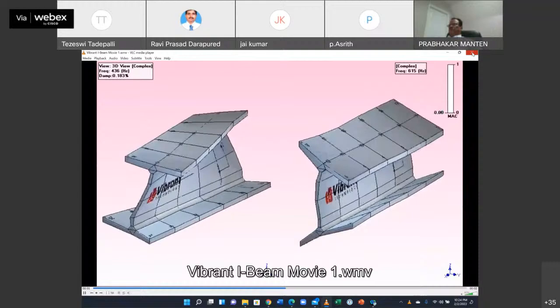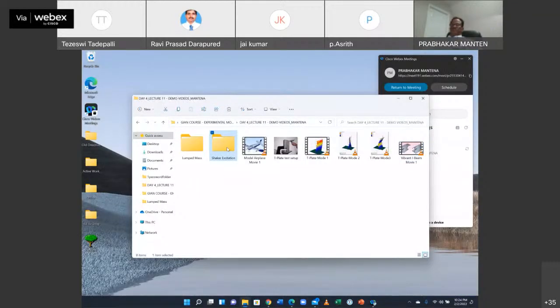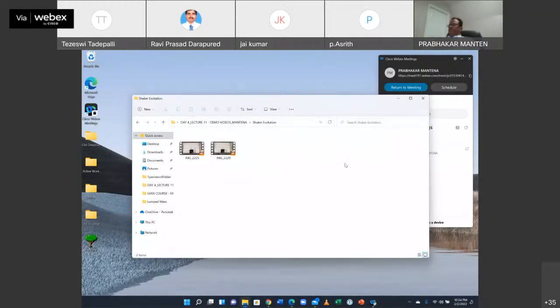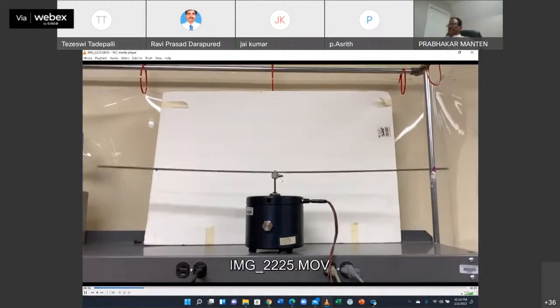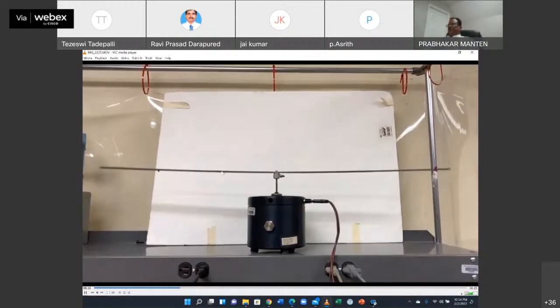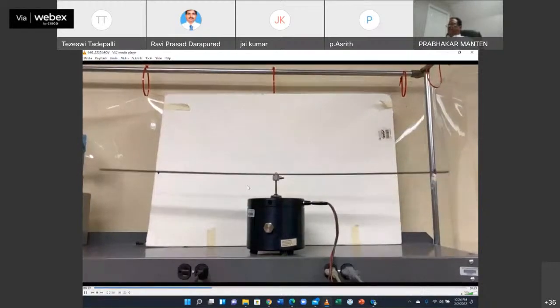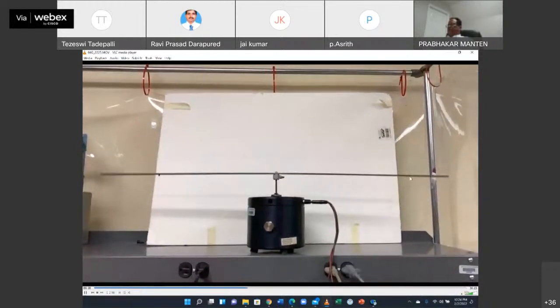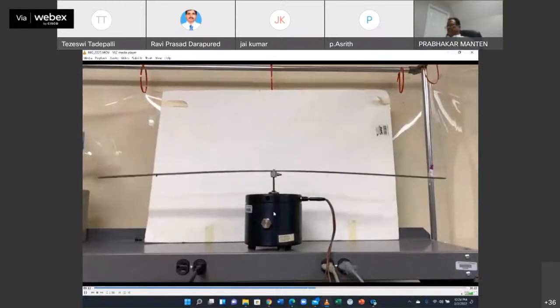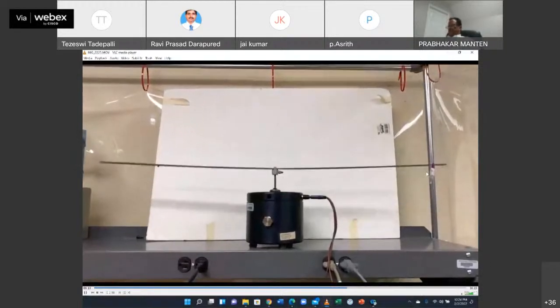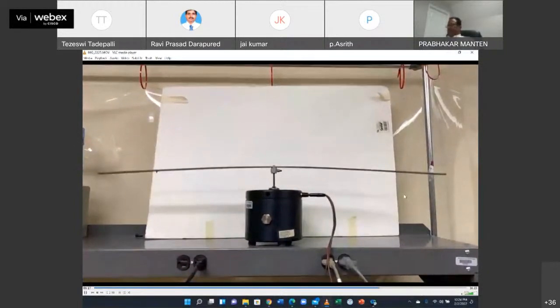And I think I have one more example, shaker excitation. This is one more thing we do in our lab here. We use a shaker setup. Tej knows all this. He has been involved with all this. So when the forcing frequency of the shaker coincides with the natural frequency of the cantilever beam, dual cantilever beam, this is the fundamental mode, the first mode. Theoretically, we make them calculate this. It's easily doable. Boundary conditions and the formulas are there.